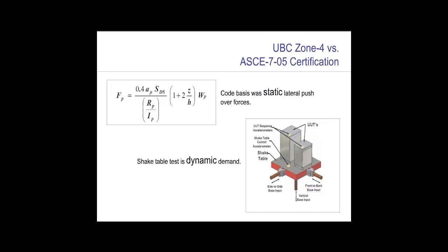Therefore, it is imperative that the consultant, the contractor, the end user, and especially the AHJ be informed as to what documentation is the proof and basis for the seismic qualification certificate. Many reputable OEM firms that have been in the industry a long time still advertise that they are seismic qualified, but further in-depth research often reveals that this statement is based on the old UBC calculation static force method and is no longer valid.